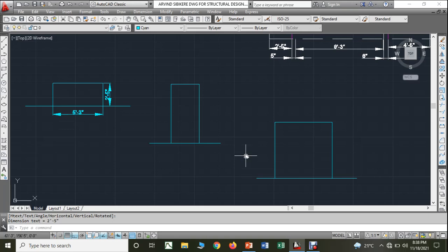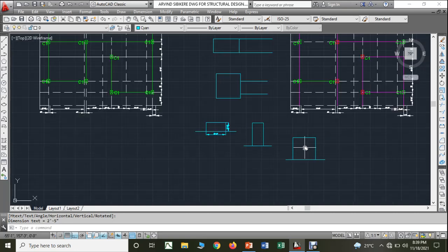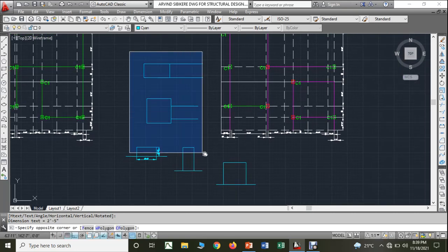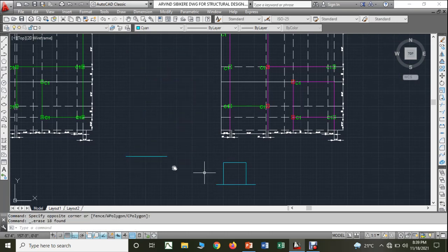Then based on how many beams a column is going to connect, how many are primary beams and how many are secondary beams, based on that we will again orient the positions of the columns. Since that option is possible only in the rectangular column and there are so many advantages, we are going to consider the rectangular columns only, compared to circular or square columns. Similarly, in this project also, I am going to consider all the columns as rectangular columns only.